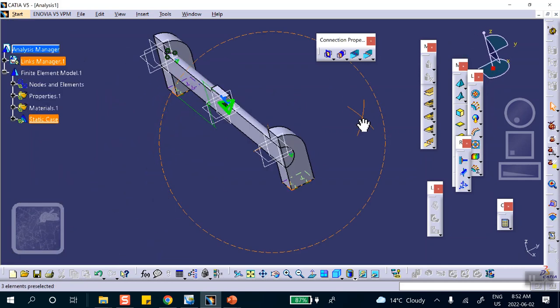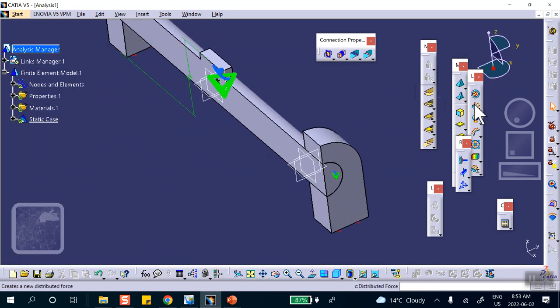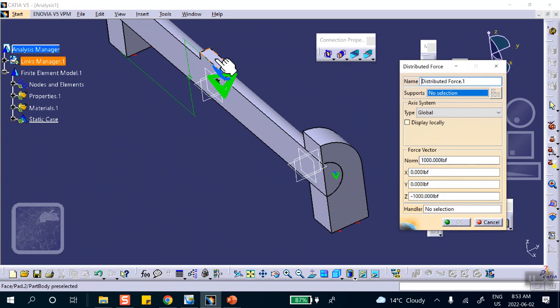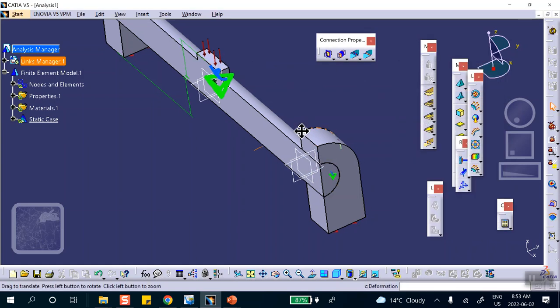Okay, so let's put a load here. And remember, if you are dealing with a force, then you divide whatever the force is by 2. Okay, so let's pretend that there was 2,000 pounds here. I think last on Tuesday it was 2,000 pounds of the whole thing, or 1,000. Anyway, divided by 2. If it's pressure, leave it the way it is. Okay, so good.